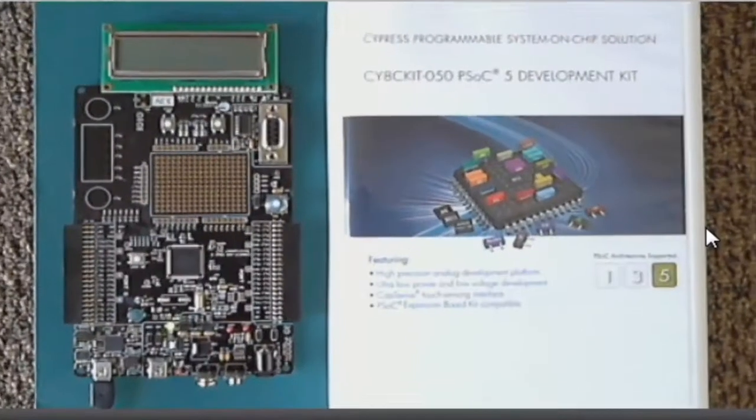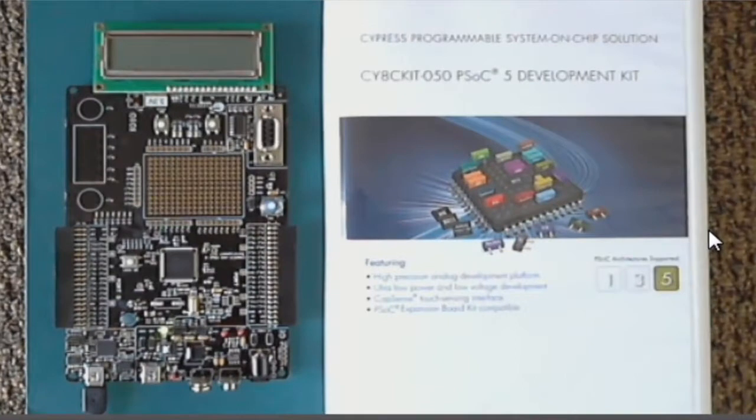We now switch our view over, seeing our development board as it goes through the programming process. That 1 Hz clock being hooked directly to the pin should show us a blink at 50% duty cycle at 1 Hz. That's as easy as it is to create a project and download it using the PSoC Creator development tool.